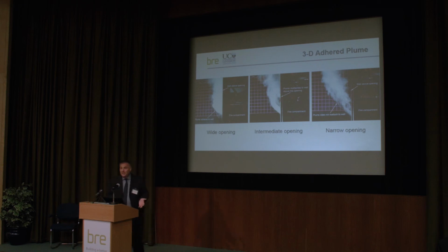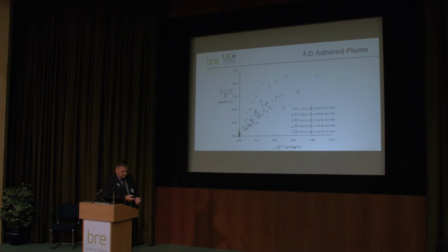So I thought I'm really going to struggle here to get a single equation representing all of this. Again, here's the data. Same thing, increasing height, increasing mass. Without going into too much detail, it's the same type of behaviour. There is more scatter. We're getting more entrainment for the narrow plumes because they're projecting per unit height of rise compared to a wider plume that sticks. Again, I use the same method in characterising different entrainment regions. And amazingly, this data collapses down to a single relationship as well. Perhaps I just got lucky, I don't know, but it works.